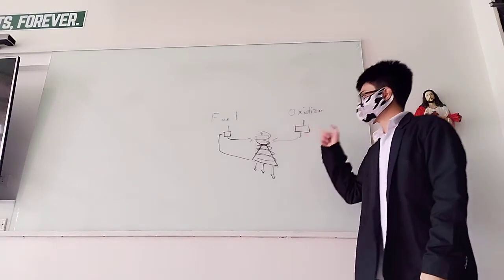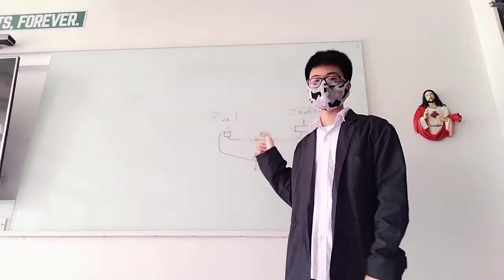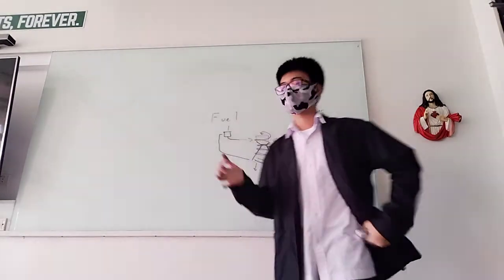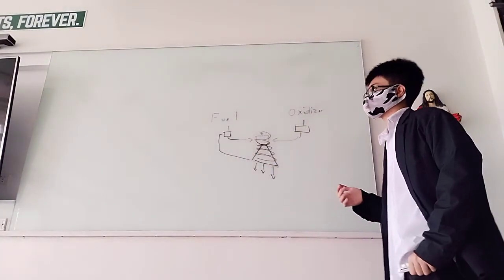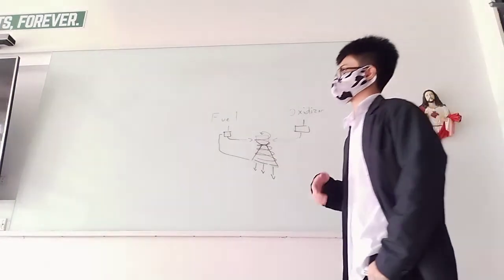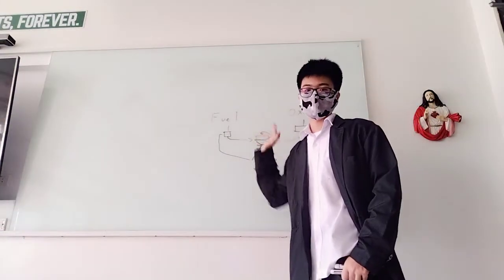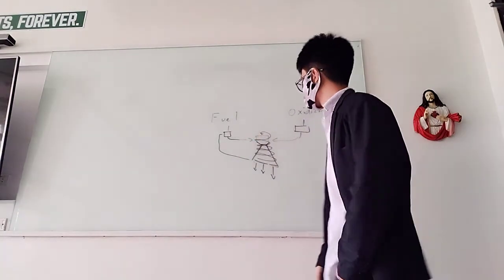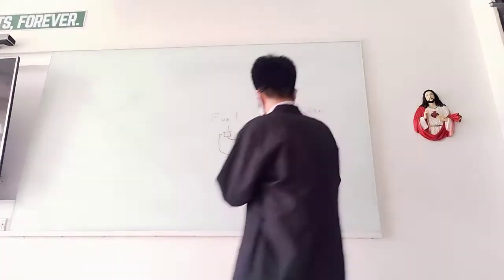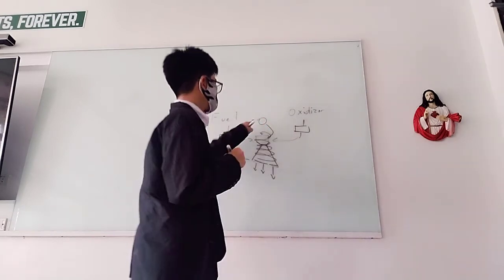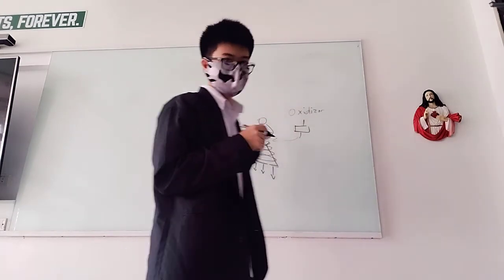In fact, this is what SpaceX uses in their Merlin engine. They cool the RP1, or the fuel. RP1 is refined petroleum, and it's rocket grade fuel. And then they run it throughout the engine nozzle and back into the engine. And then they have some igniter fluid, probably I think TEA-TEB, that is fed in here that initiates the reaction.